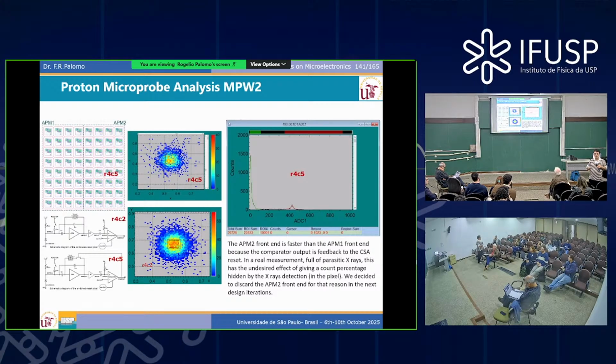Basically we chose that beam used there for PIXE. They use 2 MeV protons because they are most efficient against aluminum layers to generate X-rays. It's a few kilo electron volts, but it's calibrated. So basically the layer they use as an aluminum target to generate PIXE has a similar thickness to the metallization of the chip. So the X-rays are basically the same.